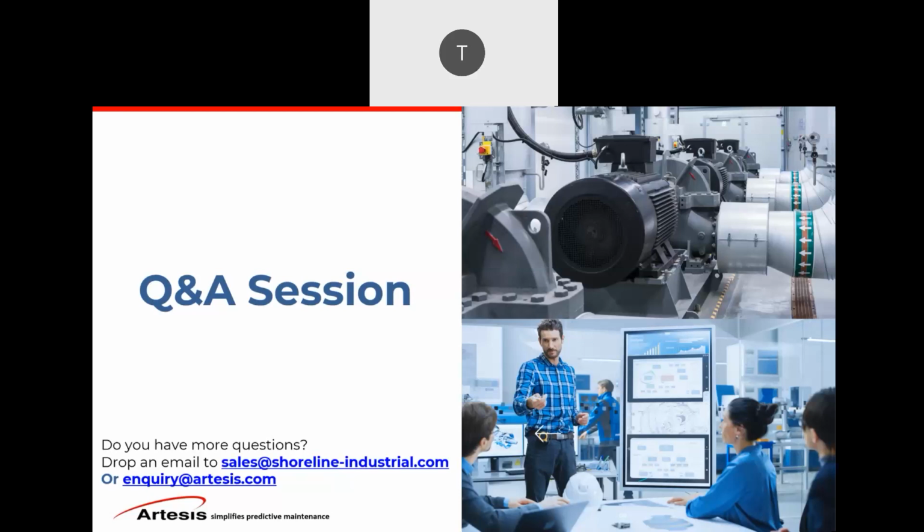Would the Fmax frequency be different? No, the Fmax would still be right now 1250, whether it's 60 hertz or 50 hertz. But we have plans to increase this sampling rate to 10 kilohertz. Then Fmax will be 5 kilohertz, regardless of the motor speed or frequency.